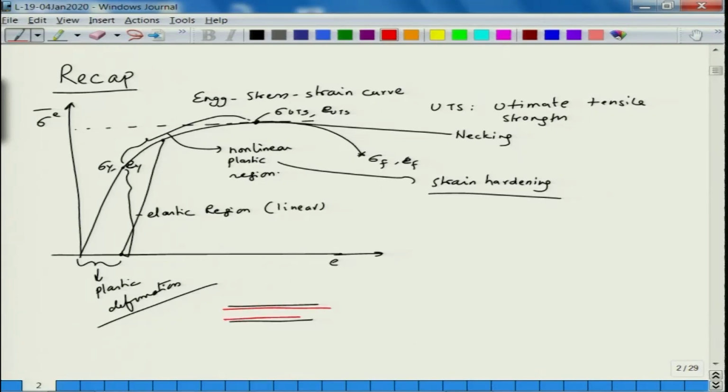So, when you deform the sample, it goes from this state to, let us say, this state, gets thinner, and then somewhere after this it undergoes formation of a neck, something like this. So, this black one you can say is A, the green one could be the point B. So, let us say this is point A, this is point B, and then you are at point C. So, the red one will be the point B and this will be point C, the green one. So, this is the point at which the neck starts to form, and so this is where necking starts.